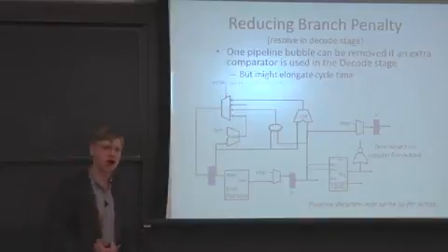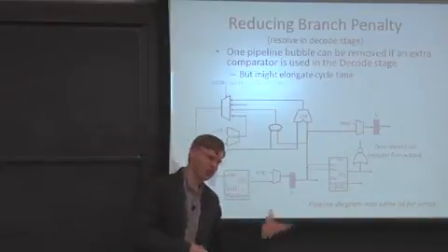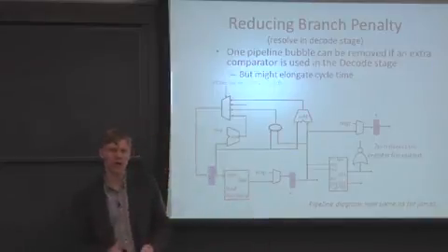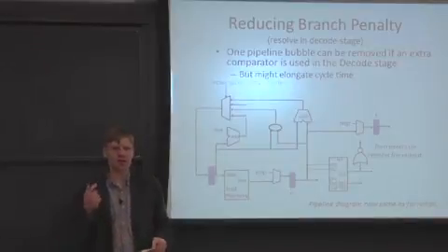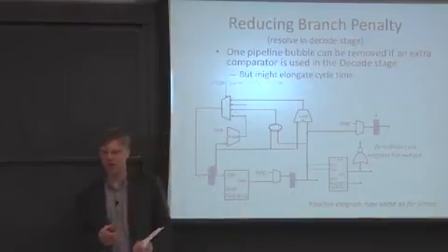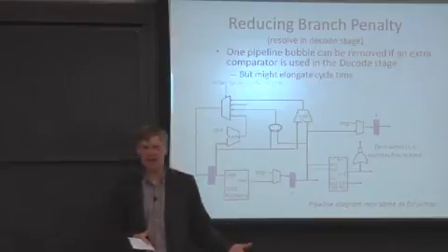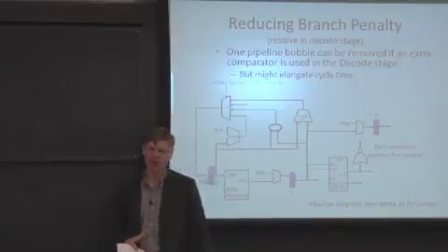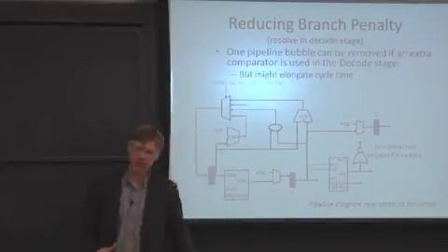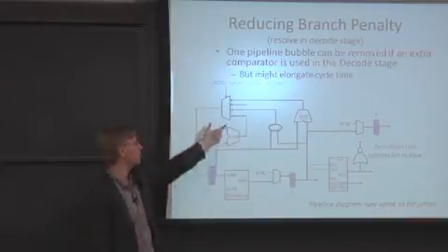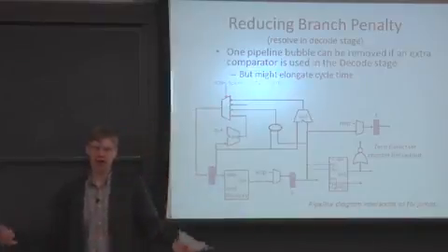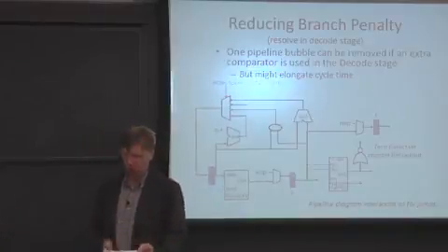And as we talked about in the iron law of processor performance, you can get performance either by lowering your clocks per instruction, or by increasing your clock frequency, or lowering your clock period. So these two things trade off. You can elongate your cycle time, which will negatively impact your performance, or time per program, in our iron law of processor performance. But on the flip side, branches resolve faster. So your aggregate clocks per instruction, especially for branches, will go down.